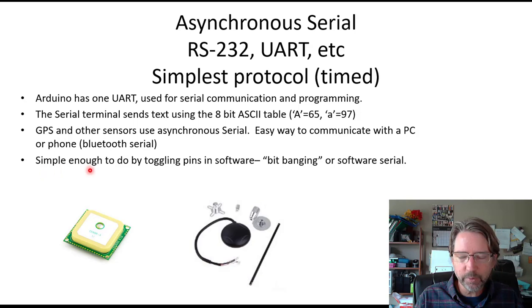It's a simple enough protocol. You can actually just do it by turning the pins on and off yourself in software. So if you need more serial ports, this is one approach. It's called bit banging in the hobby area, because you bang out each bit in your 8-bit number by hand here. The built-in serial port, you can just send it a number and it will handle it in the background for you, and it will also receive in the background and store the data until you're ready to read it.